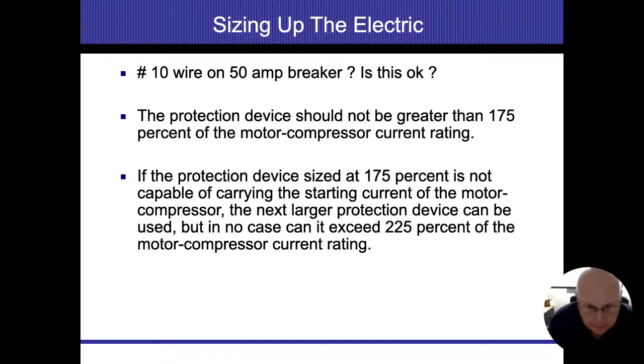But let's take the central air conditioning systems. And for us in residential home inspections, where we're going to see overfusing is typically going to be the central air conditioning system, well pumps, and electric radiant baseboard heat. Well pumps, we're not going to see the data plate, so we're just not going to know what size wire and what size breaker it calls for. Electric radiant heat, not always are you going to see that either. All right, you have to start taking things apart and dismantling them. And we really don't do that to see it. But air conditioning systems, on the other hand, you can see those, all right? And we can take a picture of that data plate that's on there.